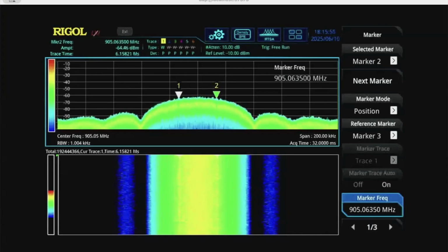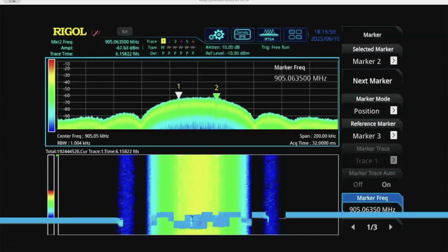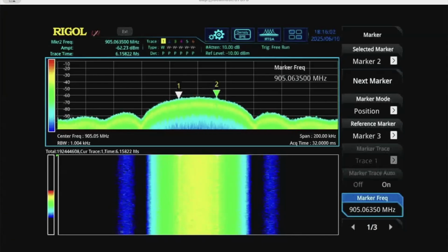You can see that the vast majority of the energy in this signal is in this main lobe. That is a hallmark of minimum shift keying. Like we're talking lots of energy in the main lobe. I see ever so often people say that you don't even really need much of a filter to filter out the other lobes, the other harmonics. So of course in practice you're still going to filter, but your filter requirements are not that harsh. So you're not dealing with a signal with a lot of energy in side lobes.